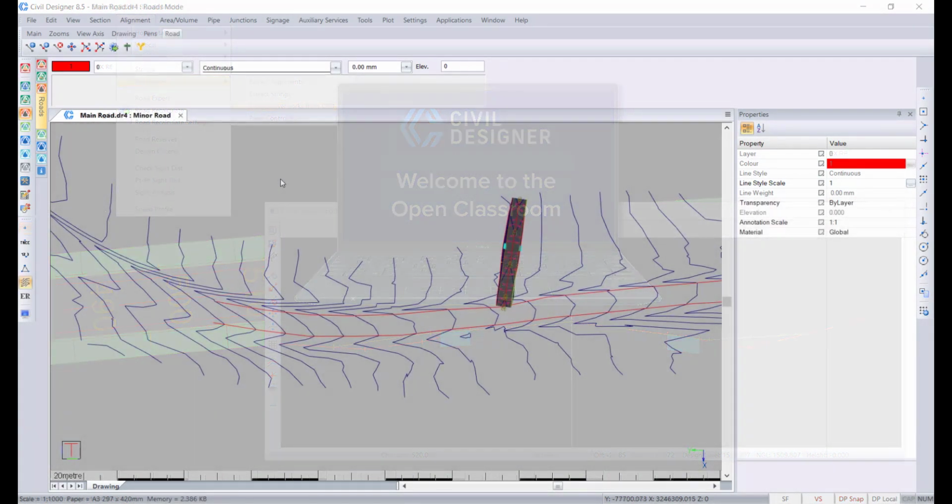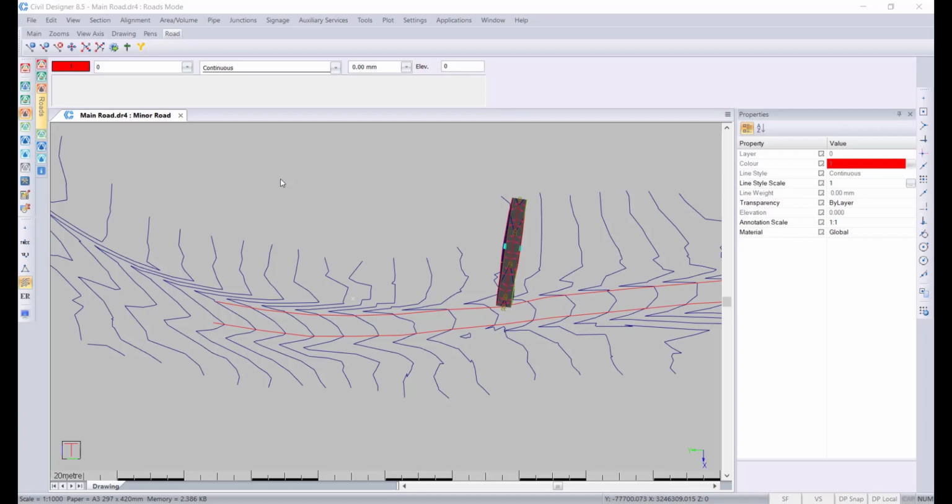Thanks, Charles, and welcome everybody to this webinar. Today we're going to be looking at three main items which will be tying into an existing road. So you'll be looking at speeding up your design of your main road that you're tying into. We'll then be looking at specifying the layerworks that are going to be added to the road. So that will be between the existing edge and the new road edge. We'll be defining those with polylines. We'll then be looking at control points and how to make side drains with a taper off to the side using the control points. Let's go ahead and have a look.